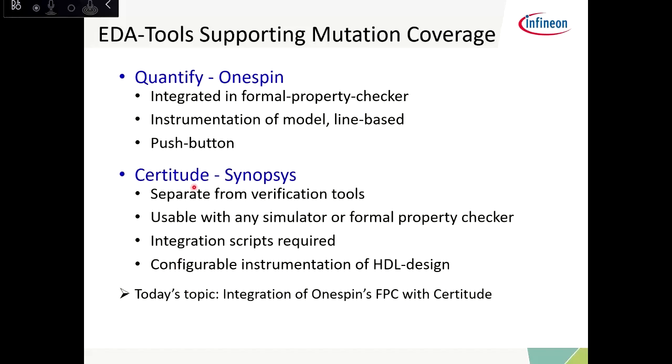Certitude is a tool from Synopsys, which instruments the HDL code of RTL designs. As the instrumented design can be read by HDL front ends of any kind of verification tools processing RTL designs, it can be integrated with a wide range of simulators and formal property checkers, even in mixed verification setups, providing common and combinable metrics for all of these. However, the integration is non-trivial and requires deeper knowledge about Certitude and the specific verification tool. Certitude also allows users to choose the configuration of the instrumentation. However, it should be ensured that the common configuration is agreed upon in the organization you work in.